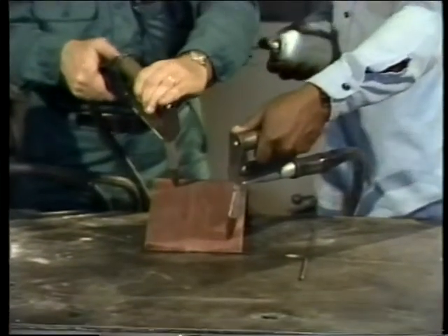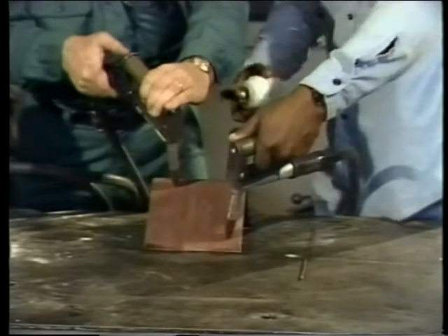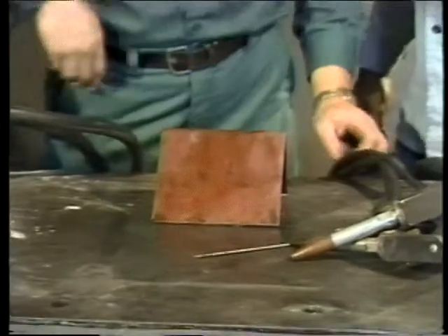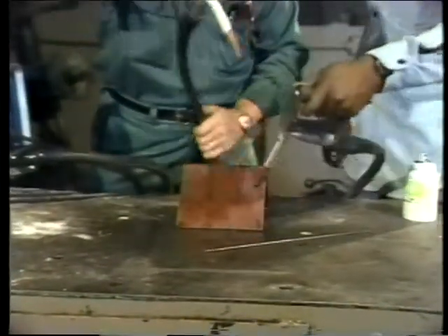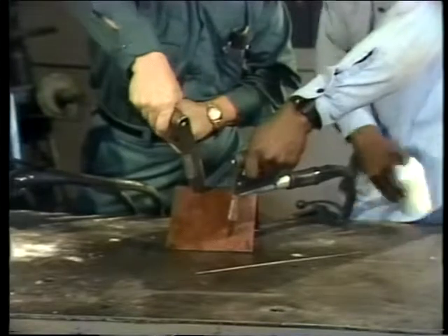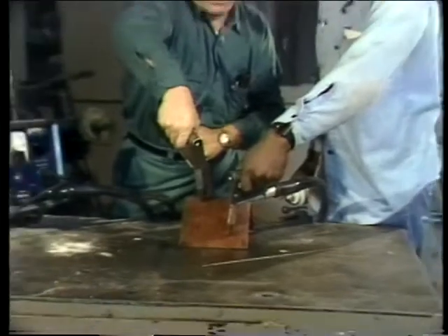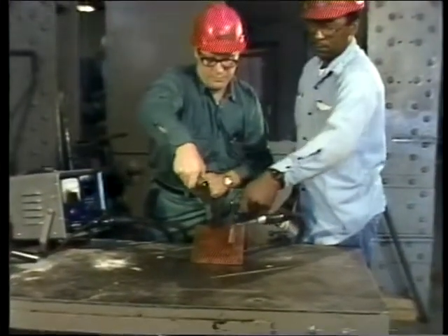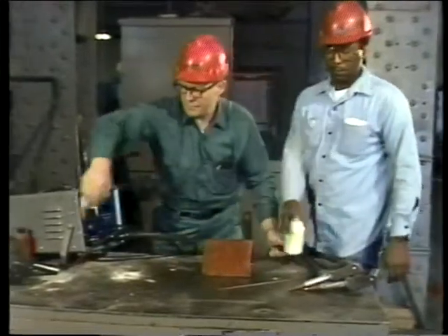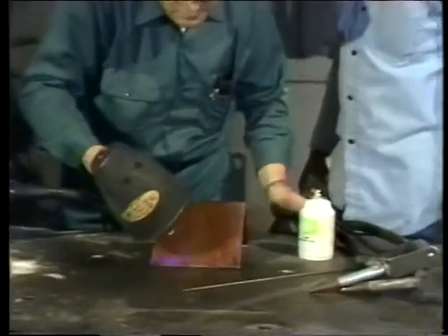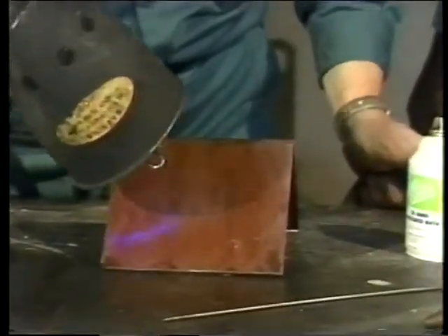For a contact shot, it's extremely important to make the connection tightly. If they aren't tight, the contacts will arc and try to weld themselves to the part being tested. And once the current is set at the appropriate level and contact is secure, the magnetic field is energized from the remote control on the probe's handle, and the particles are sprayed on. If visible particles are being used, the indication of a flaw would show up immediately. But since we're looking for hard-to-locate flaws, we're using fluorescent particles in this test.